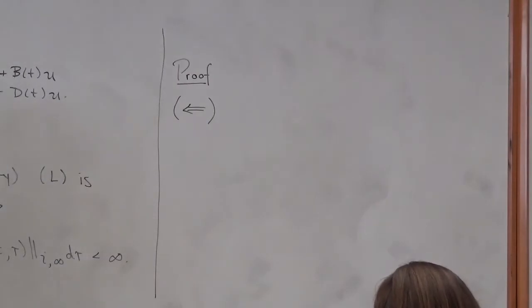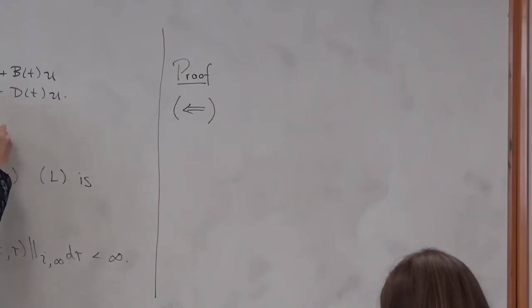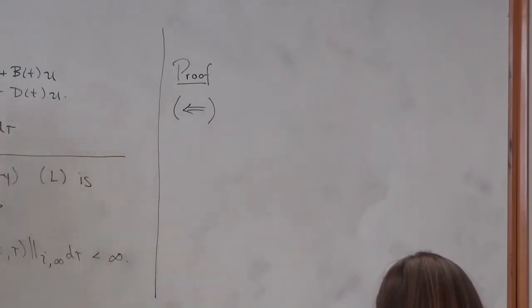All right, so from what we did last day, we know the relationship between y and u. So y of t is the integral from minus infinity to t of h of t, tau, u of tau, d tau. Right? That's our input-output response based on this weighting matrix, weighting pattern, weighting function.